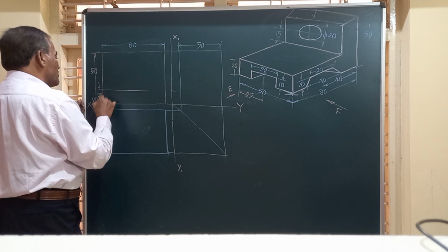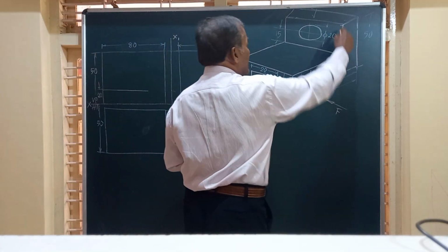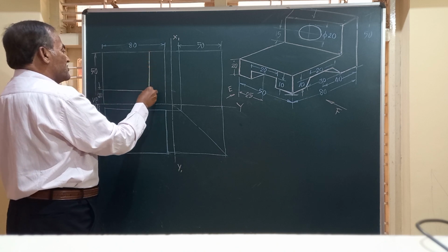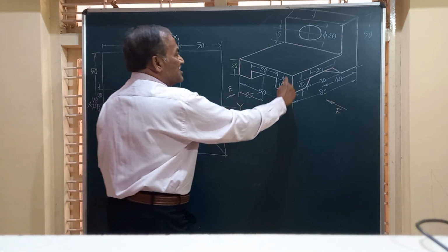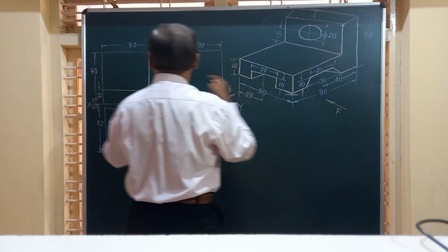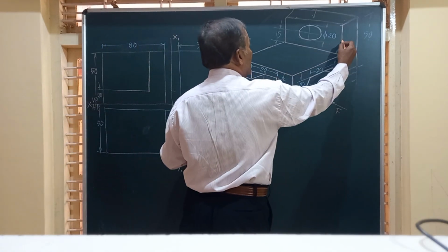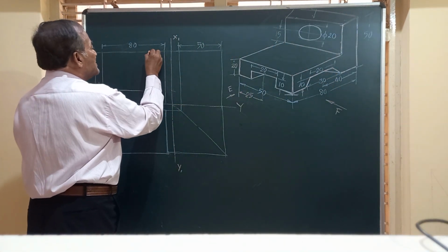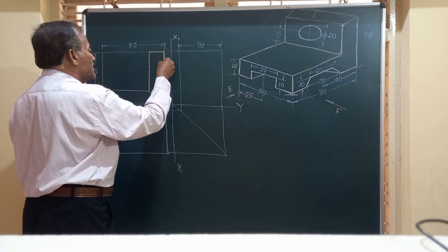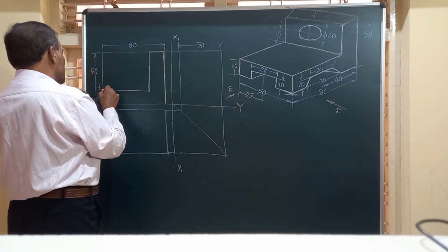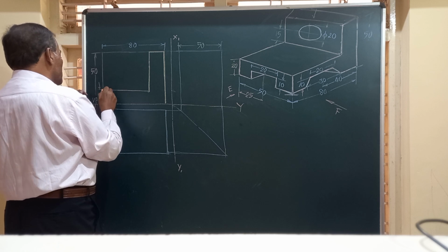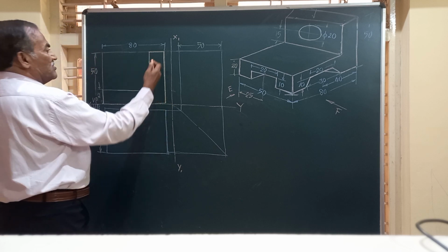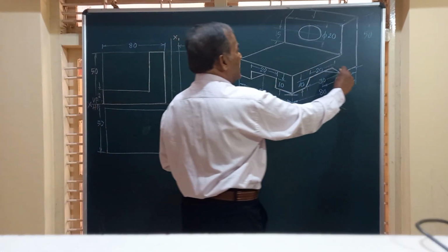And here I draw a vertical line to get this inverted L shape. I have drawn a horizontal line, a vertical line through that to the given height of 50 mm. Then I am completing the portion of that solid by drawing lines like this. Friends, this is how this L shape of the object looks.